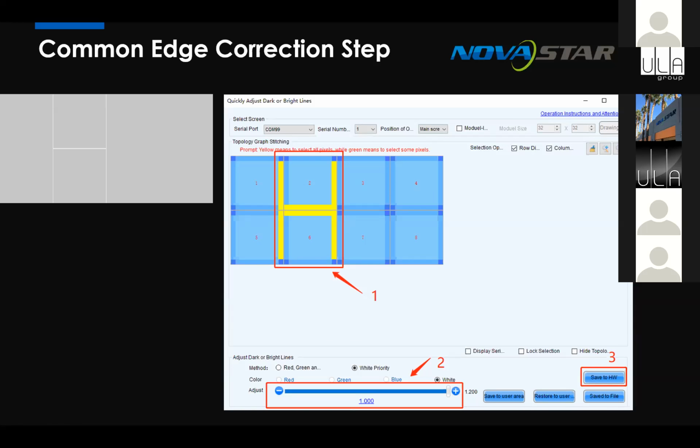One of the other things you need to be cautious of, if you're running Windows, is to make sure that you haven't got any desktop scaling turned on, because by default now on laptops, Windows will change the scaling to be higher than 100% to make it look nice. You need to ensure that your desktop scaling is set to 100%, otherwise it's not going to line up properly. But once you've done those two things, in essence, this grey square should match the exact pixel spacing of your screen. And once you do that, you'll get this option here that'll show the cabinet sizes on your screen.